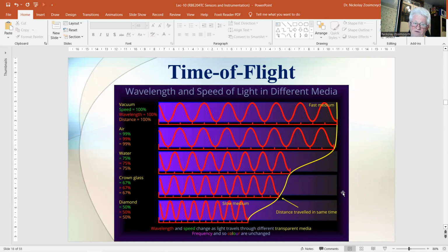So the TOF of a light pulse is very short, roughly 3 nanoseconds for each meter, or 6 nanoseconds for a distance of 1 meter to a target and back. The measurement of short distances calls for fast electronics to obtain a reasonable resolution. For long range, resolution is not a major problem. The boundary is mainly set by the decreasing intensity of the reflected light at increasing distance, and hence the reduced S/N ratio.